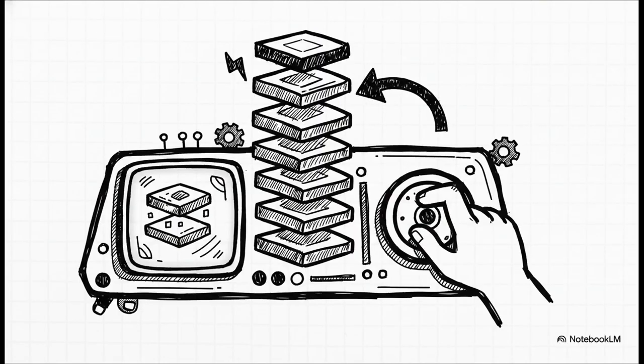Now, here's where it gets really cool. In modern microcontrollers, like the PIC-18 series, the stack isn't some hidden, off-limits thing anymore. They give you direct hardware access. You get special registers that let you literally see and even change the data sitting at the top of the stack. And another register always points to exactly where that top is. This basically turns the stack from a simple plate dispenser into a programmable power tool.